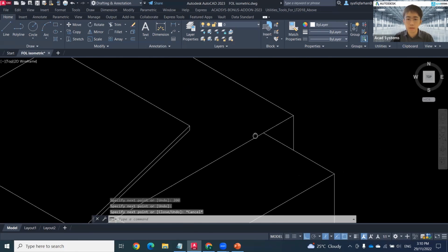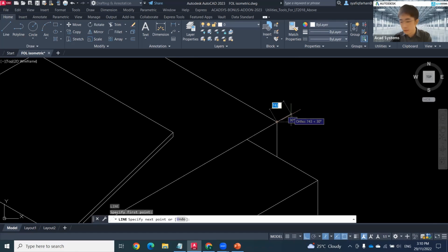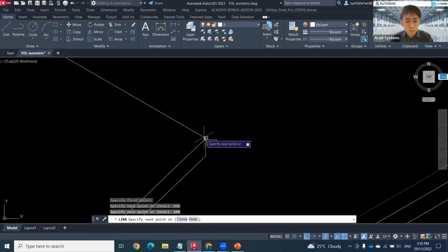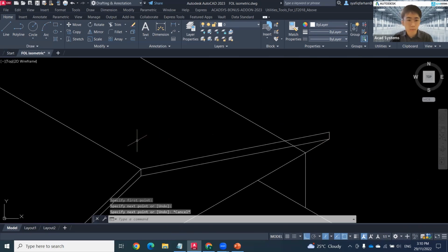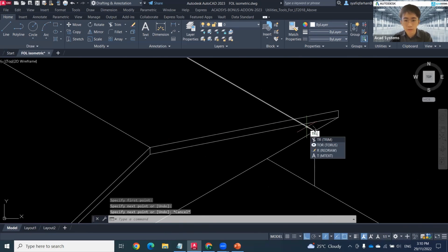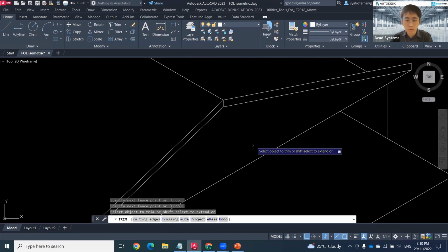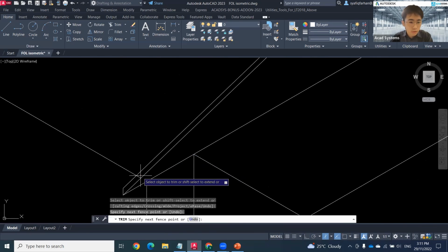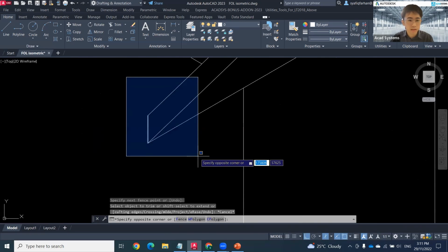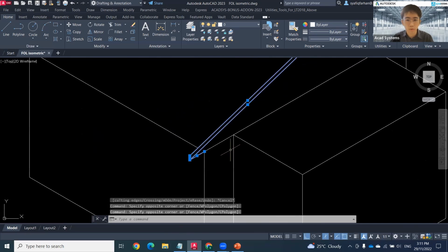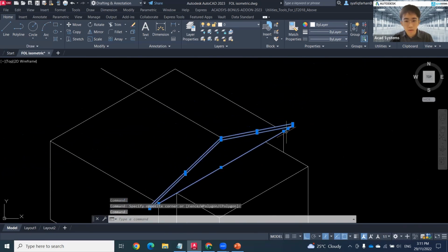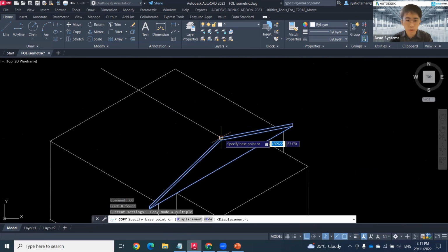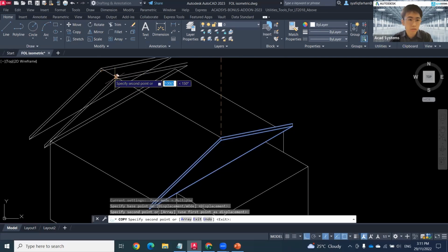And we can do the same thing at another side. 800, 200. Here, draw the line here. Then we can trim this line first, and these two lines here. Then we can use these blue selections and then this green selection to select these few lines. Okay. Then we type CO in our command bar, copy, select the base point, and place here.